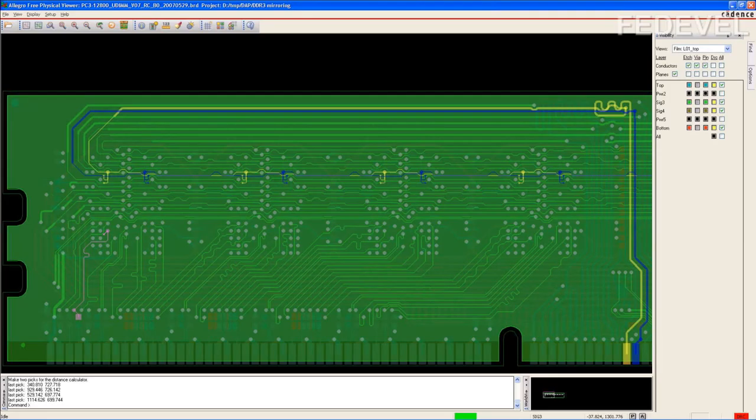So don't forget one more time, for the flyby topology, it is very important that all the signals which are connected to all these memory chips, they need to be routed from the processor or FPGA in some kind of tolerance to this first memory chip. What kind of tolerance? Read in the design guide. If you don't know, use our magic number 10 mils.